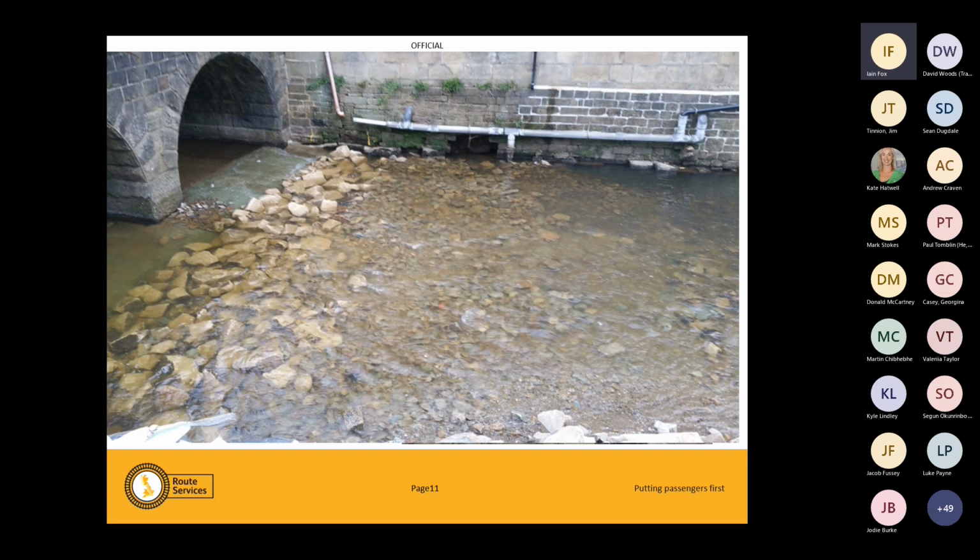A ship's propeller fires water out the back of the boat. Therefore, that water is moving faster than it normally would in a marina. Therefore, there is going to be a risk of scour. The boat launch ramps often get undermined and collapse because when a speedboat gets launched, the first thing they do is open the throttle, and that washes away the under part of that boat launch ramp. So they quite often require a lot of works.